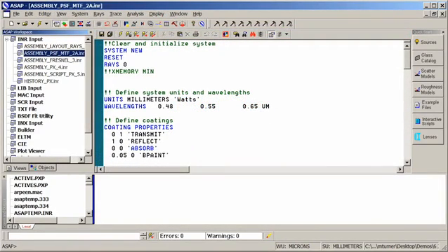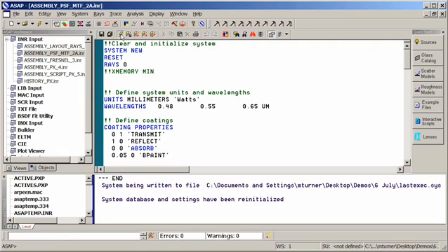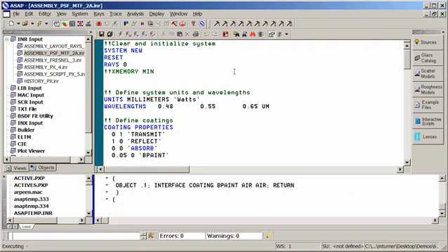The next thing we're going to perform is to look at a point spread function and an MTF calculation performed within ASAP. We can then take this information and compare it to the data from the original optical design program to make sure that indeed the translation was proper, the mechanical structures aren't significantly impeding the performance, and that the optical materials are properly defined, as well as the optical components. I'm going to run this file and we'll take a look at the output.